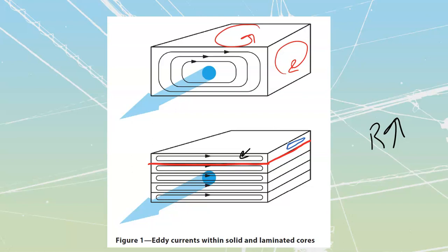As far as core construction goes these days, cores are going to be made up of multiple laminated layers. The more layers that they can place into these, the better the construction of that transformer. But at the same time, you are going to have an increased cost that goes along with slicing that steel into smaller pieces and laminating them all together. As far as the windings go, the windings are often placed around a bobbin or a spool, and then they're placed into the actual transformer core.